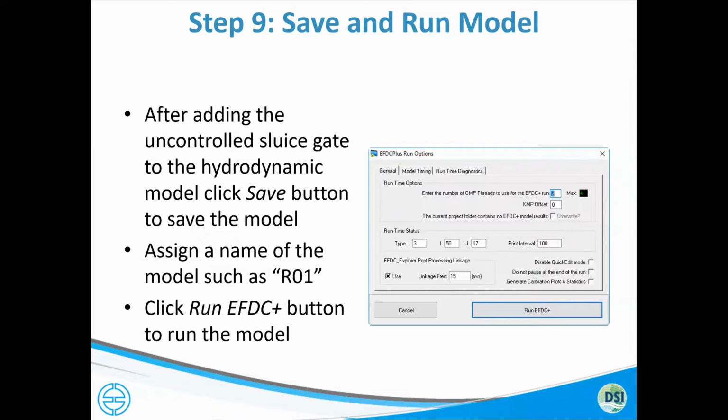We have a whole separate presentation on how to use multi-threaded applications and get the best throughput for your particular example. But in this case, I'll just tell you that 4 threads indicates that there are 2 actual physical cores. So this is your typical Intel i5 system. And to get your maximum throughput, you just enter half the value of your threads.